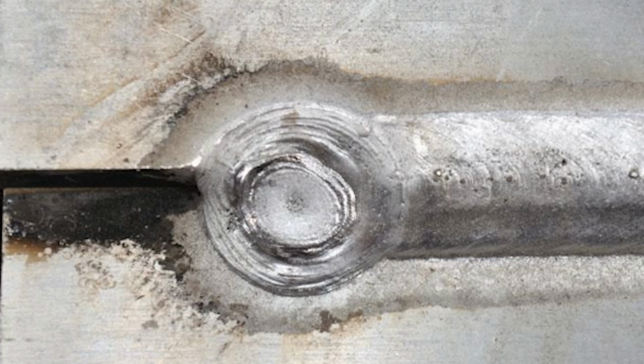When I started doing Schedule 10 and thinner stainless pipe with fusion welds with TIG, I didn't realize how common it was to have a crater pipe where you'd have a hole that would leak straight through the material. And this is a direct result of tapering off the amperage too fast. Now with pipe welding, where you typically use scratch or lift start and you're not able to slowly decrease the amperage at the end of a weld, you're going to get the crater pipes really bad, especially on thinner material.